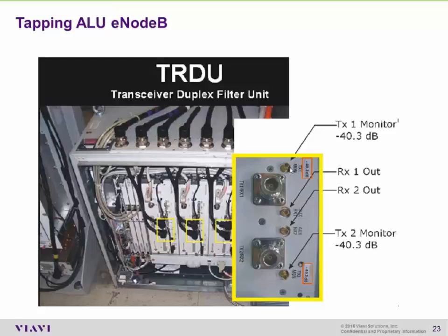Again, they're 1.0/2.3, 50 ohm. There's also the same thing, 1.0/2.3, 75 ohm, but the ones that they use are 1.0/2.3, 50 ohm. These are 40 dB down test points. This helps protect the instrument using these test points when you're looking at the signal quality out of these transmitters. But even with these attenuated test points, you still often need in the order of about 25 to 30 dB of internal attenuation as part of the test set to not distort that signal.